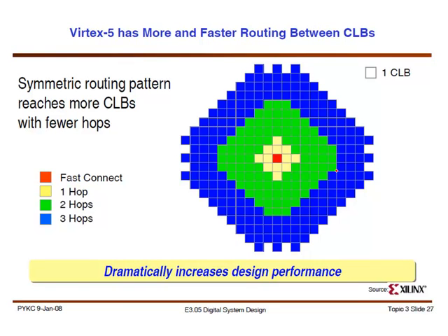Manhattan routing. So it's easier to adapt analytic placement to more modern FPGA architectures compared to Virtex 4. And that might be one of the reasons that analytic placement didn't happen with FPGAs as readily as it happened with ASIC, because when analytic placement was very hot with ASIC, that's when Virtex 4 was around. But I'm sure if Virtex 5 had been the prevalent architecture back then, analytic placement would have been much more prevalent with FPGAs.